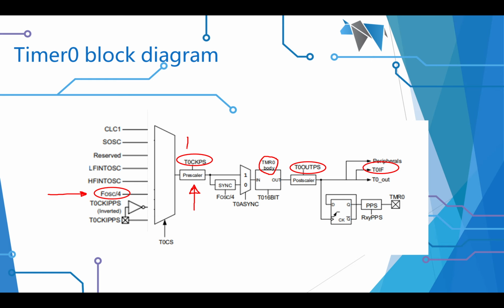And so we need to put a number in here. We need to put a post-scaler value in, so we need to put a registered value in there. And as we previously said, we need to select our clock source. Those are the 3 parameters. And you can set other things like whether the interrupt flag is set. If it is, it will raise an interrupt out on timer 0.